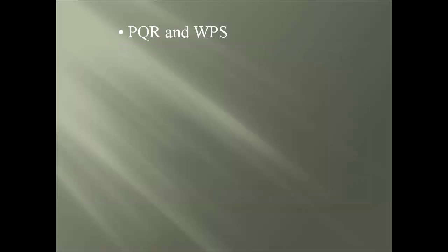Okay, we just reviewed the pre-qualified WPS, but remember, even with sheet steel, there are the PQR and WPS qualified by testing. Once again, the WPS qualified by testing is a written living document for each type of weld, which must comply with the AWS D1.3 code requirements, plus be accepted by the engineer of record.